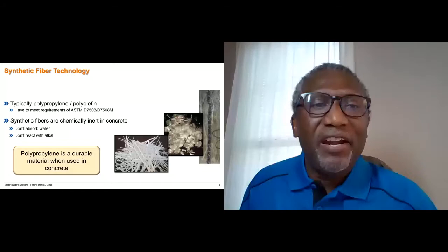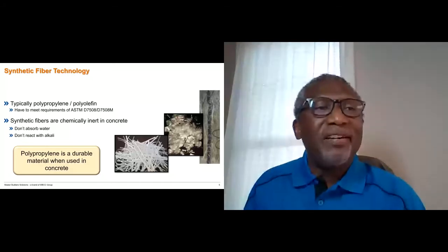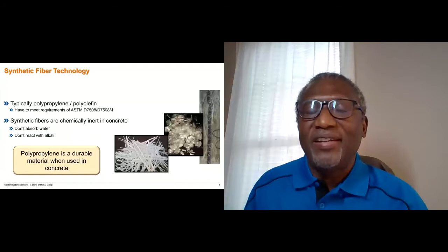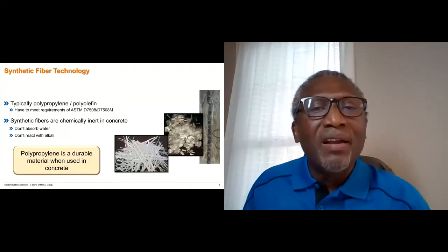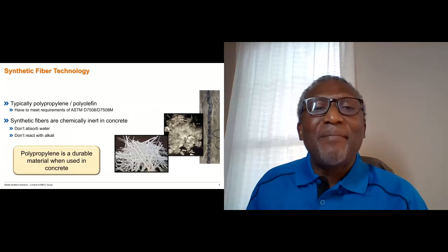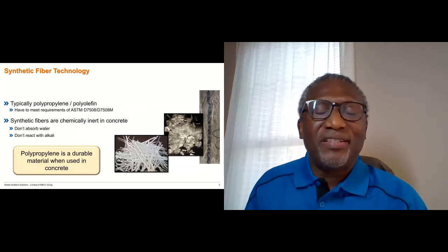And these materials, the polypropylene polyolefin, have to meet the requirements of ASTM D7508, and I'll share that with you in a minute. One of the things about synthetic fibers is the fact that they are chemically inert in concrete, the polyolefin